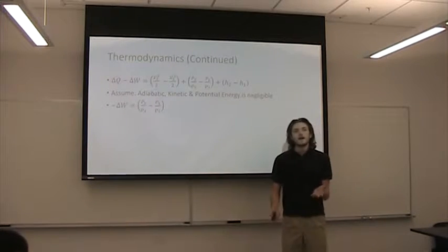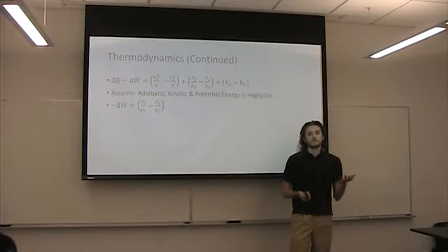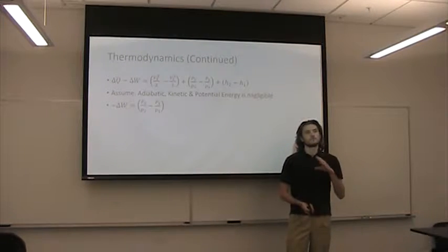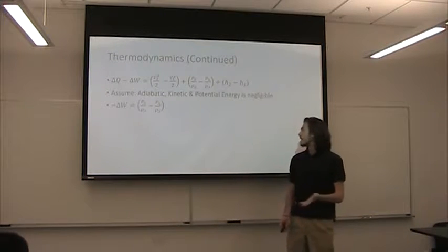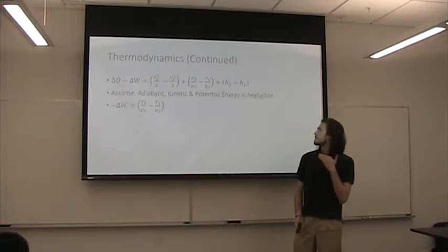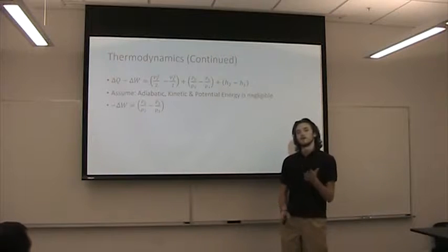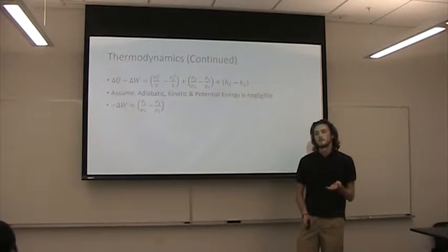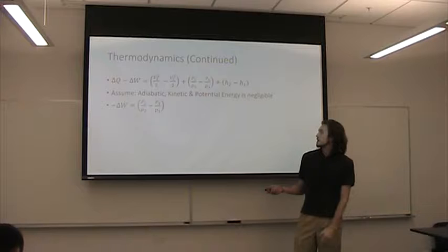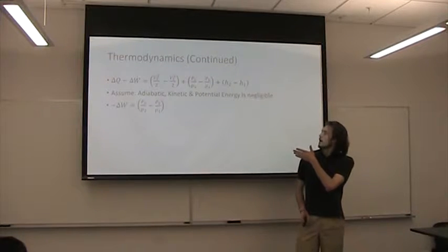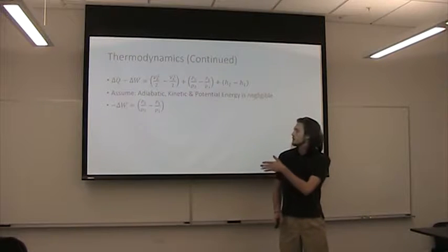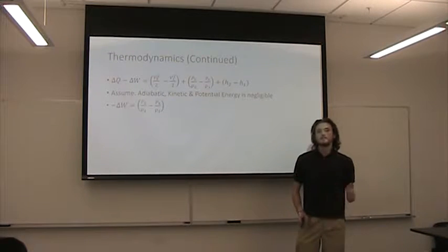So to get the work out of the process of combusting the diesel, we assume adiabatic and that kinetic and potential energy is neglected. So then we get work is the difference between the pressure over the density of each state.